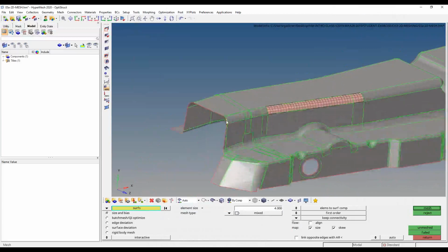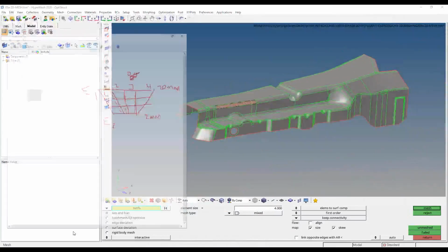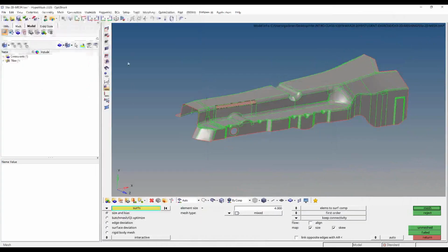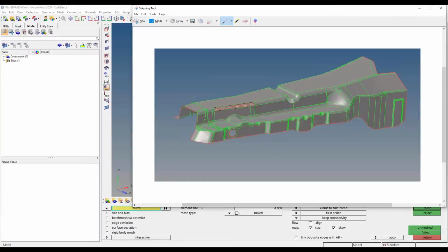What I want to be able to do in this next mesh is simulate a situation where, if I were to take another screenshot of this guy, I want to load the part on this surface over here, this bottom table. And I want to do the same thing on that back side as well. I know we're not seeing it, but there's another little line there. So we're going to load those two flanges here, and I want to see this thing start to bend in the middle.